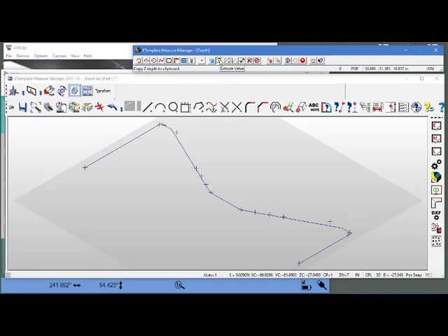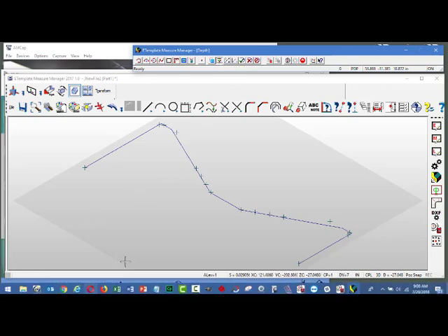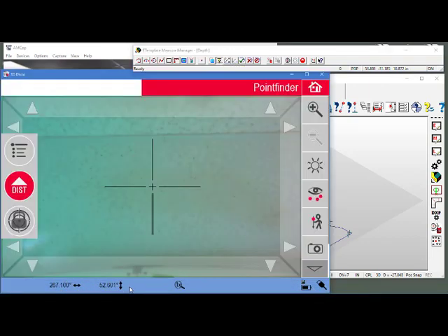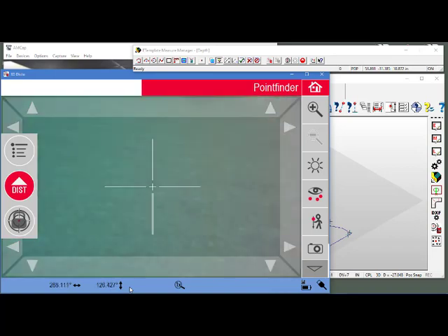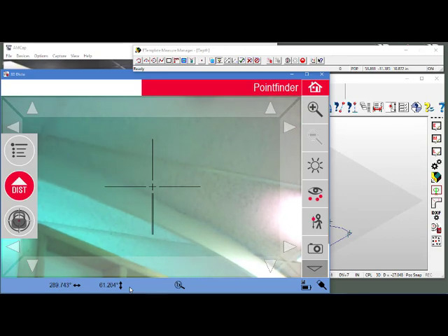In this case, I'm pointing the laser beam up at the ceiling. So I was on the floor, which is where the construction plane is. My Z depth is between the floor and wherever I hit, and I'm hitting this right now on the ceiling. And it's going to capture that height, which is shown right here. And it's on the clipboard. So next I'm going to go to my extrusion tool.